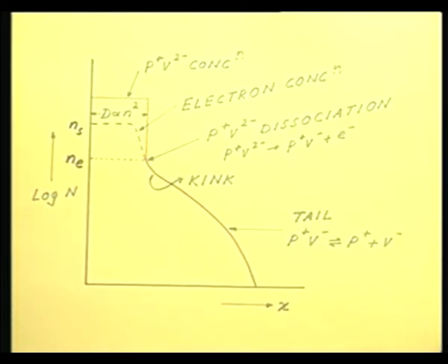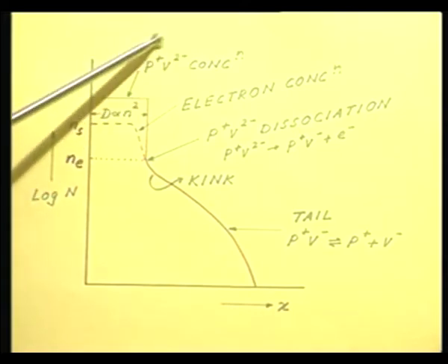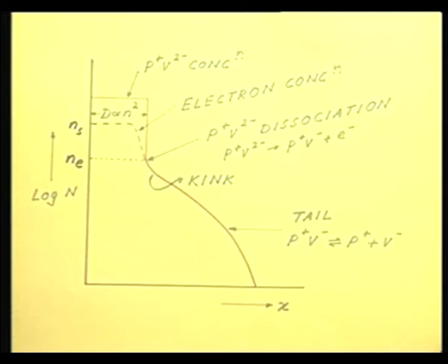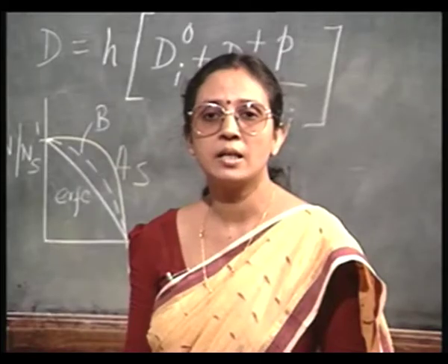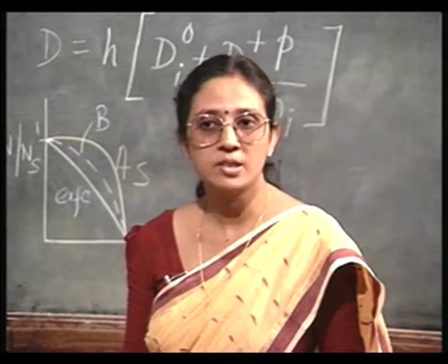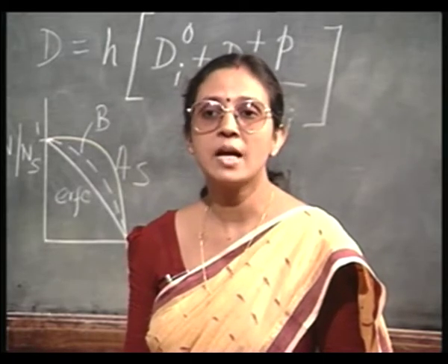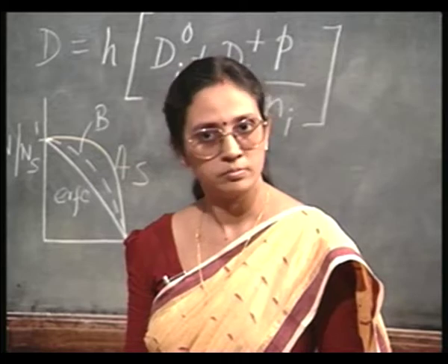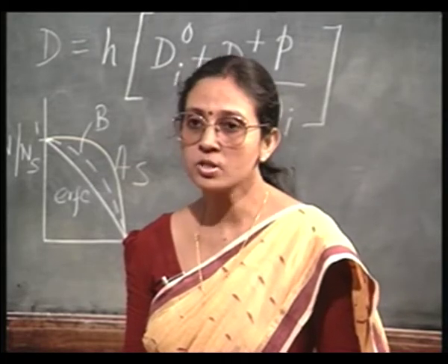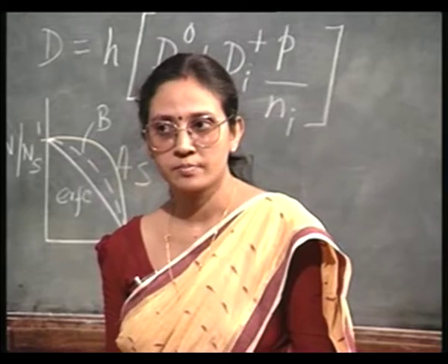As the Fermi level position changes, as it falls 0.11 electron volt below the conduction band, this pair starts to dissociate. Very simply speaking, it is something like this: doubly ionized vacancy, okay, doubly negatively charged vacancies. That means this vacancy had trapped 2 electrons. Neutral vacancy trapped 2 electrons, that is how it became doubly negatively charged, right.